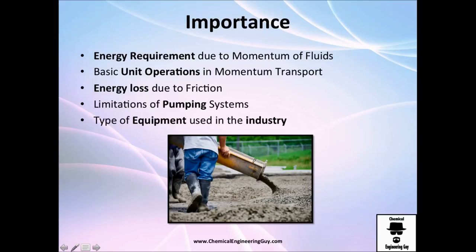So why is it important? Because we need to know the energy requirements to move that fluid. We need to know what type of unit operations are needed to do that. Do we need a valve? Do we need a pump? Do we need to measure flow? What's the friction loss of each fitting, each valve, each equipment?